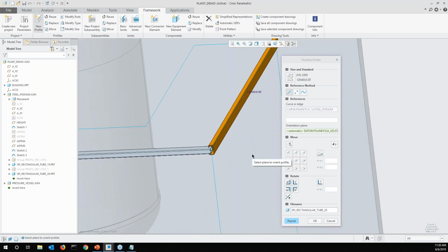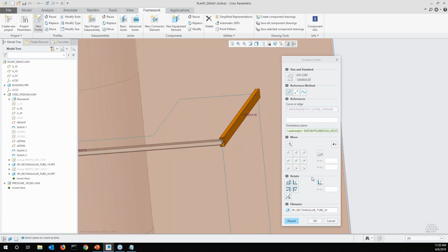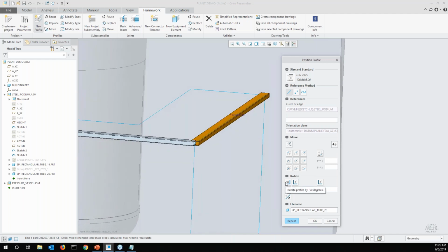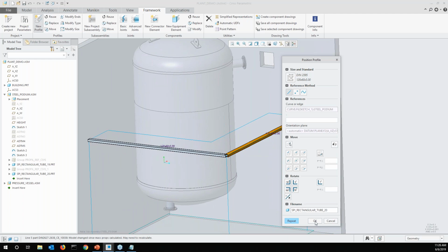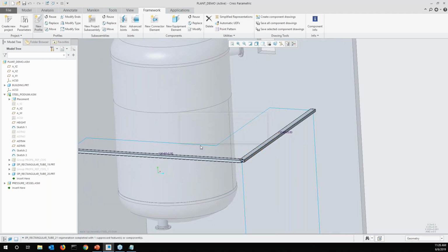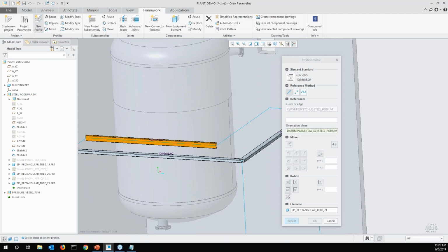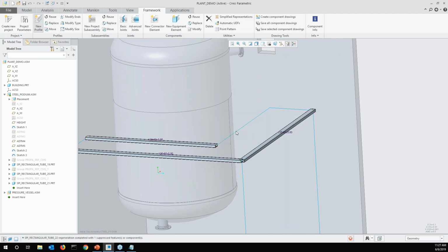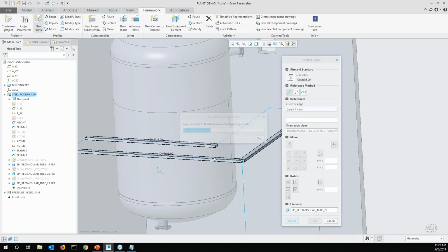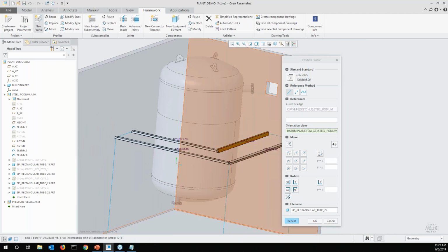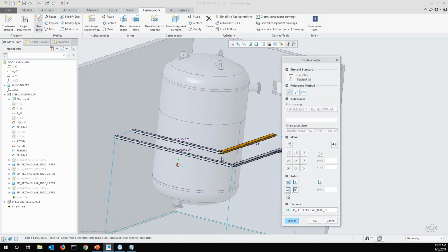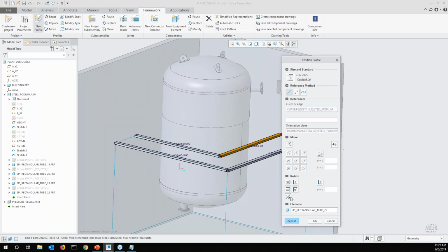And you just repeat the process and place it on a different curve, right? Now notice here that this placed the beam on the vertical axis. So this tool makes it easy to rotate that and configure it if need be. Okay, so I'll just start with those two. Actually, let's do these as well. I'll rotate that, repeat, rotate this. Right. You don't have to worry about creating any of these profiles. I don't have to worry about creating extrusion cuts for these profiles. It's all integrated within this environment here.